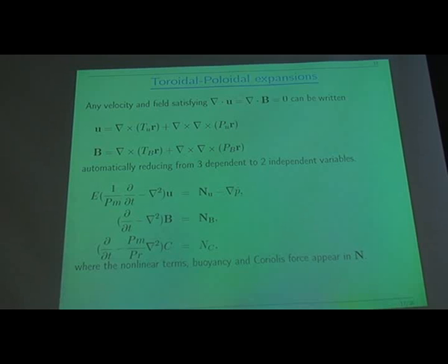If you use a finite difference code or a finite element code, you will need at each time step to correct, because after each time step you'll find that div b is not exactly 0 and div u is not exactly 0 in your computation, so you have to put in a correction at that point. Well, you actually avoid that with spectral methods, which is a nice feature of them.